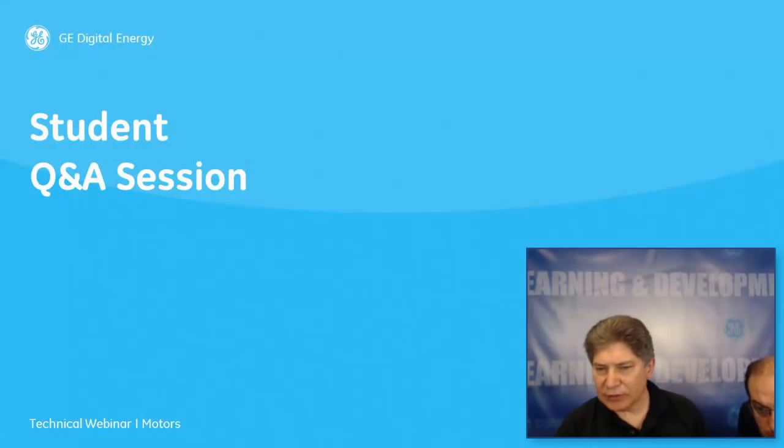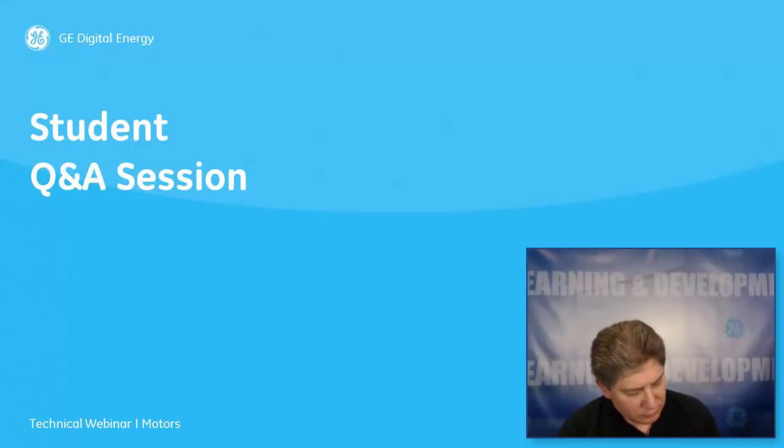Any other questions? George, it's Dennis Dixon with Chess Controls. Yes, Dennis. We have an application where we have a 1250 horsepower 4160 volt motor, and the starter manufacturer is using 600 volt class CTs. Is that a standard practice, and what are the problems that can arise?